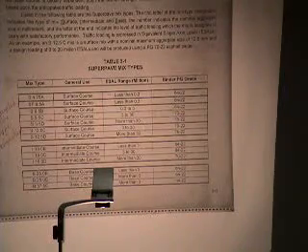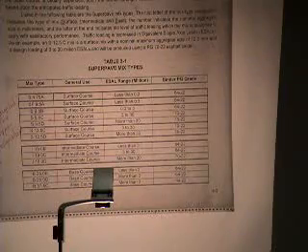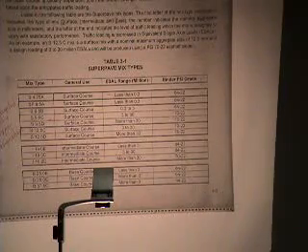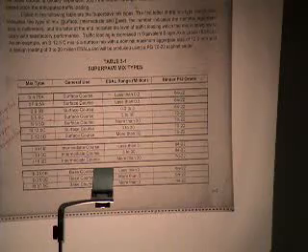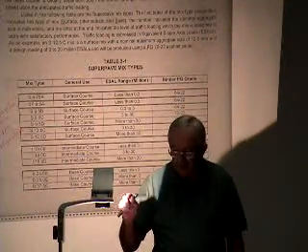Anybody ever heard of I2? The SF 9.5A is an old I2 design using Superpave criteria. It's a relatively fine mix that can be placed in a 1-inch thickness.